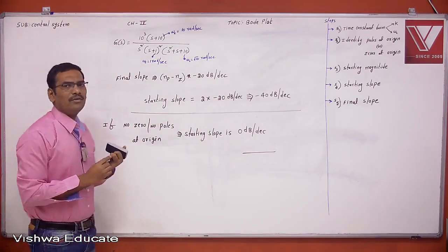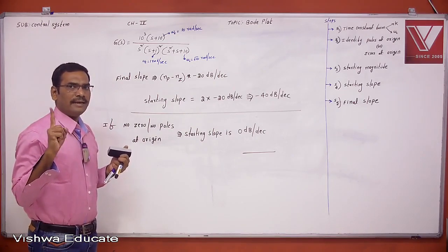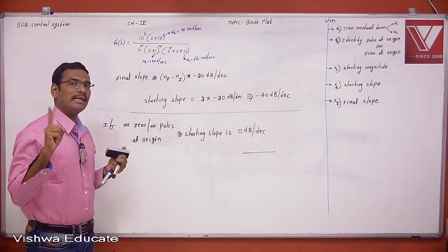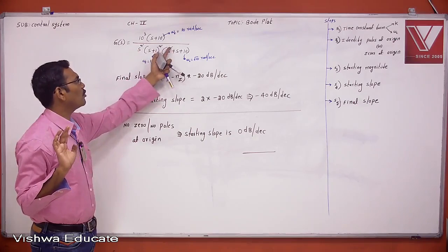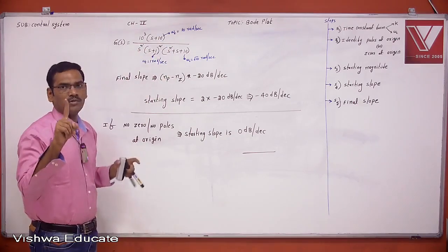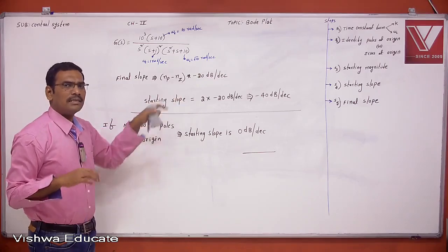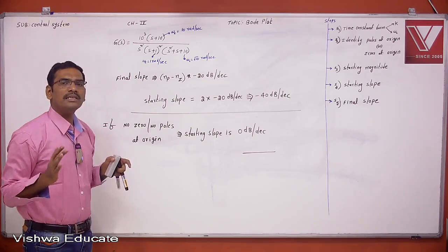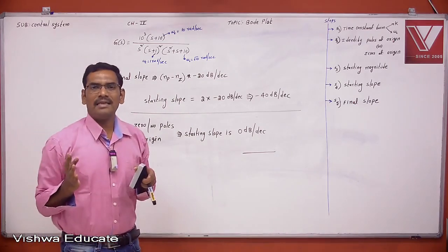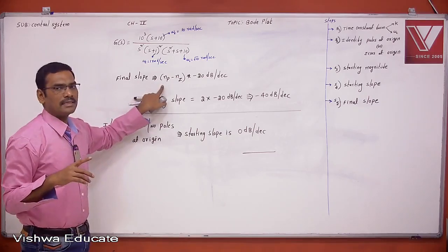Now you already know that there are three kinds of transfer function. In a practical transfer function, the number of poles is always greater than the number of zeros. Here the number of poles is 6 and the number of zeros is only 1. NP is the total number of poles, NZ is the total number of zeros. Generally the transfer functions are practical, where poles are greater than zeros, such that NP is greater than NZ. In such a situation you should take this as a formula.